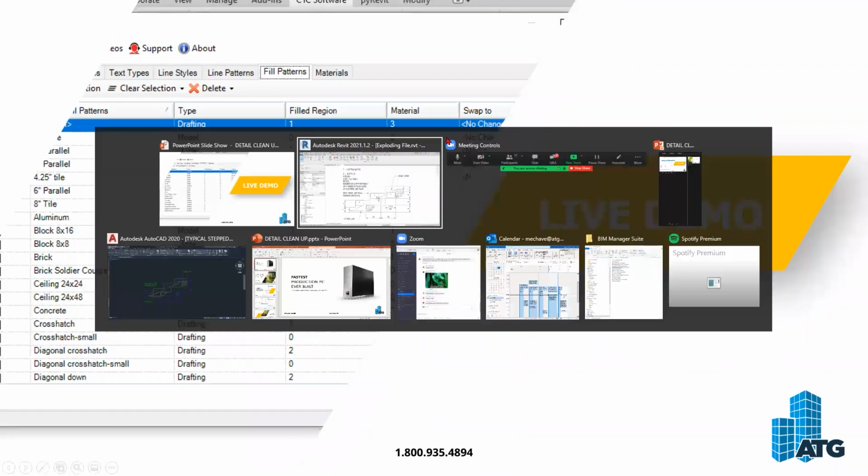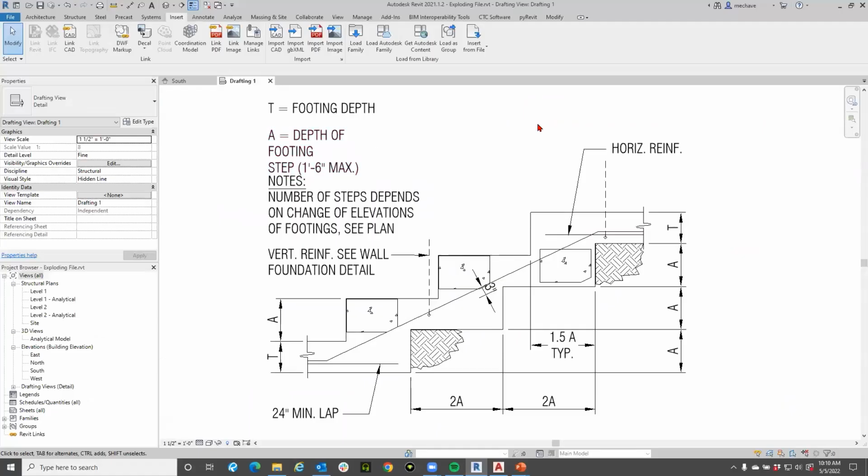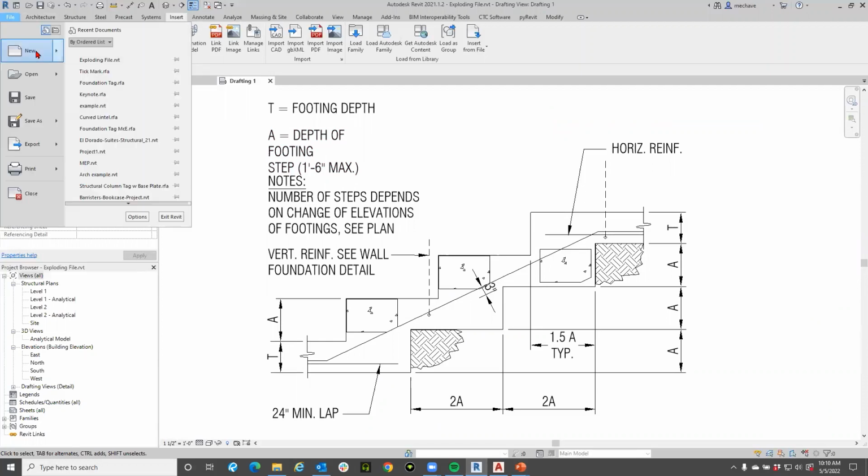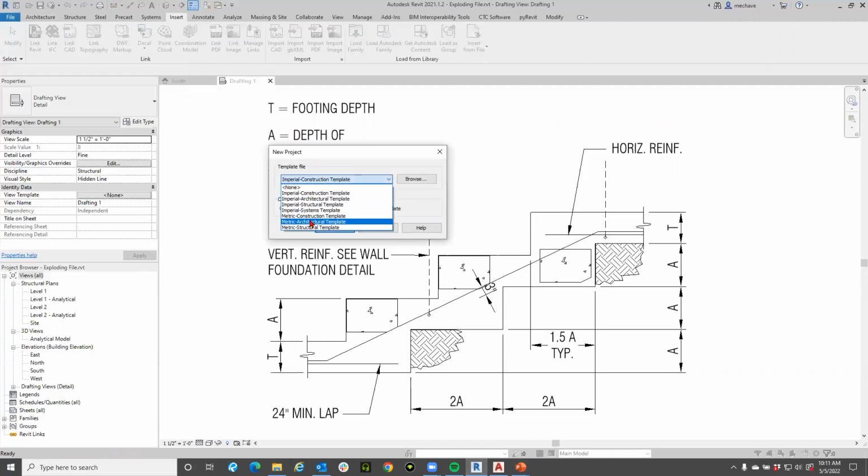Okay, so let's hop on into Revit. Somewhere in here, I have mine open. So this is a proxy project, right? This is how you want to transition your details over. You probably are going to go File, New Project from your company template. Maybe it's in here, maybe it's not. There are different Revit files, right? You have a .rte, which is a Revit template, or a .rvt, which is a project. And you can actually have a .rvt that is your template, but it's not a .rte. That's because you maybe have worksets enabled in your template, so you want to have a .rvt.